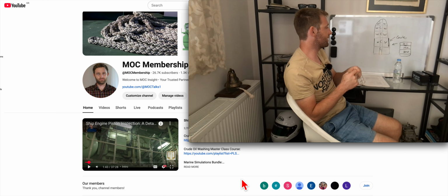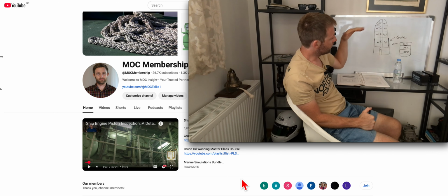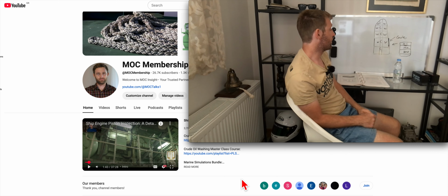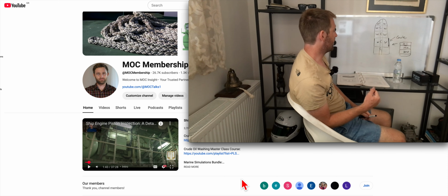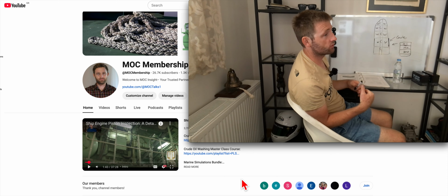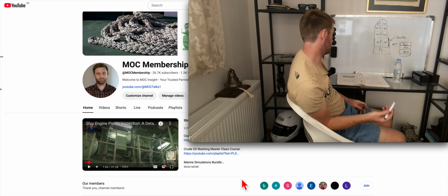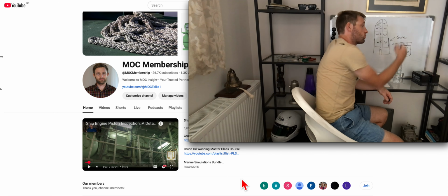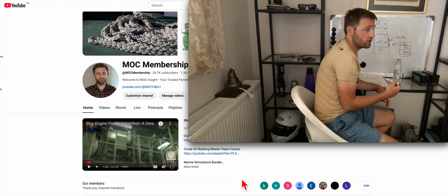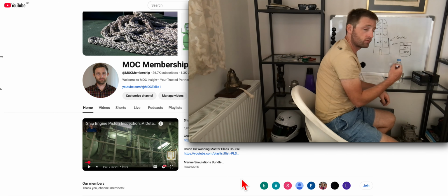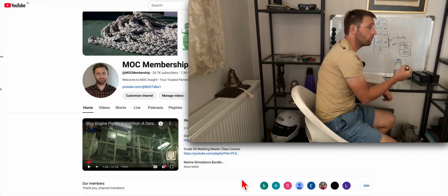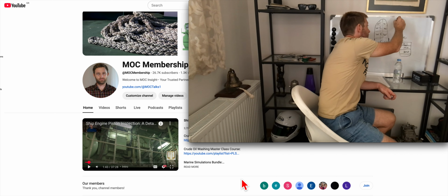And stratification means the separation of crude by temperature differences. So if you have these voyages with a huge difference in temperature while sailing, for sure it needs daily measurement of the change in temperature. This will help the chief officers at the end of the overall voyage to be much more precise on what the actual temperatures are within their crude oil tanks.